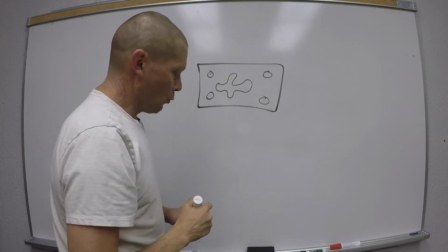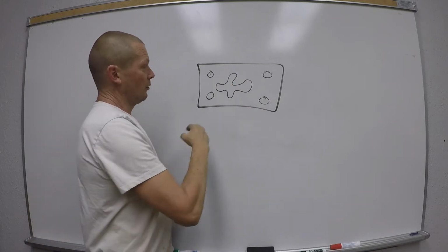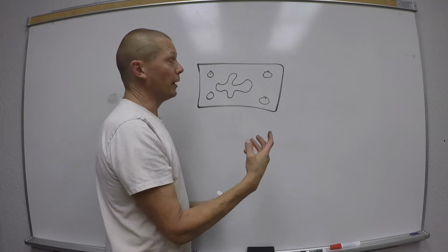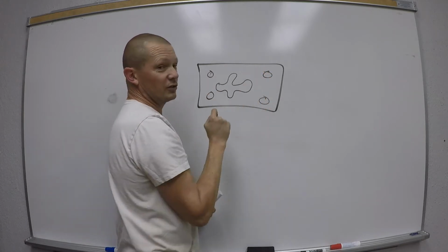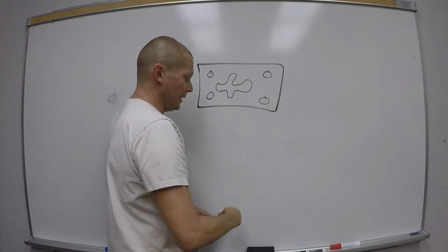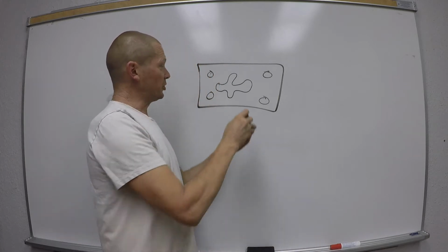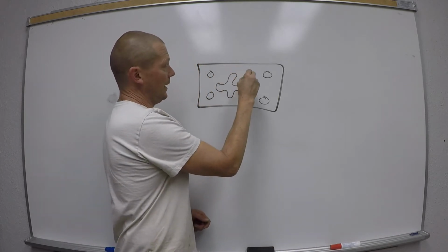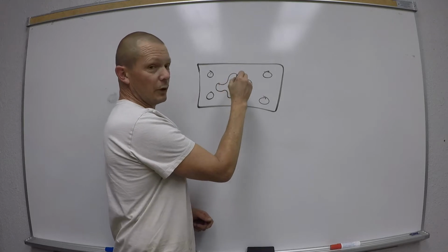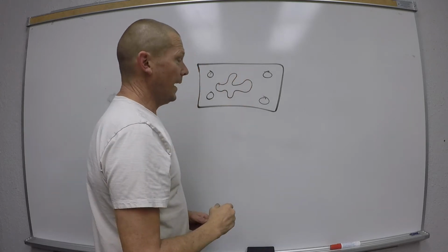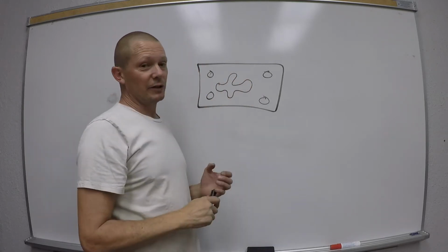We were able to tell the software, first, drill these holes, and then come in with a 1/4-inch end mill and do this profile. And it would program that.